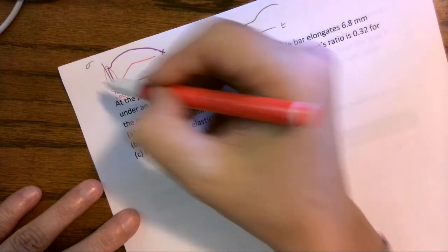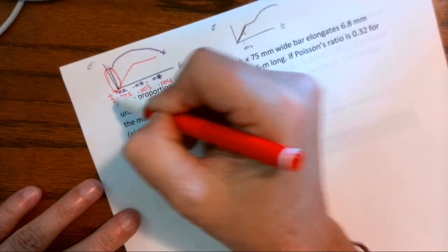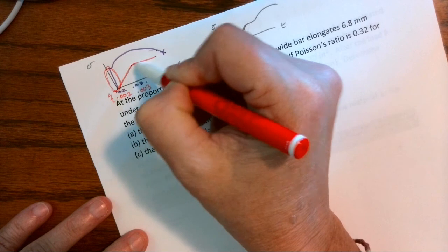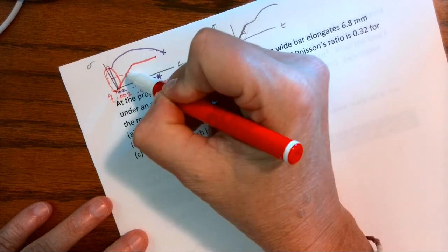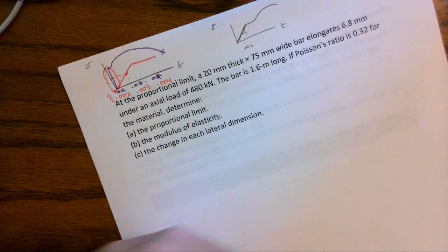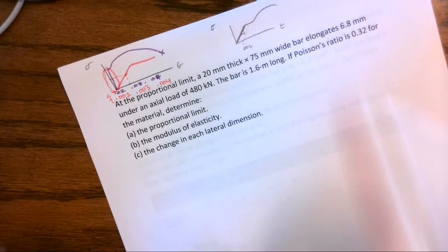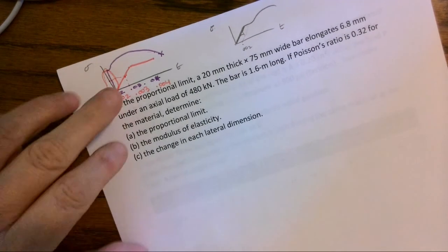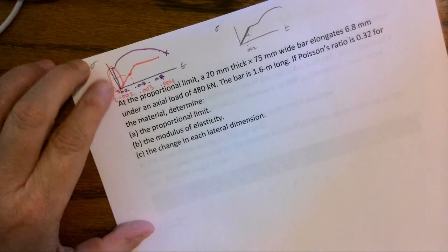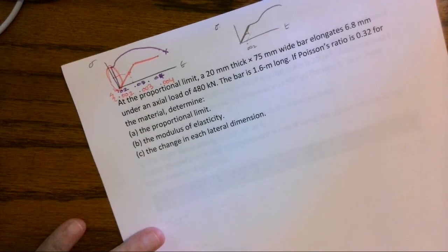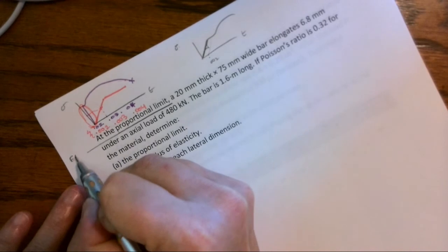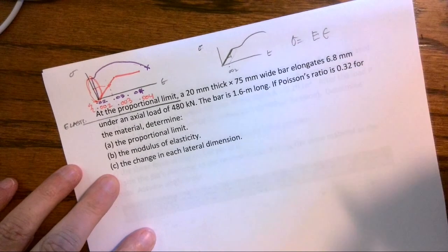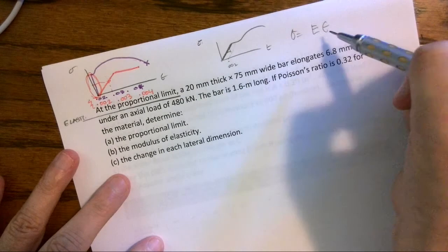So we take the elastic region, we change the scaling of our strain. That way we can actually focus in on the elastic region, so that if I want to know at this stress what the strain is, I can actually read those numbers. They're both the same material. It's just this bottom curve is zoomed into the elastic region. And if you look at the scale at the bottom, it's going to tell you, based on the color of the curve, which scale you read. Okay, so at the proportional limit, we are still in the elastic region where our equations are valid. In the elastic region, stress equals E times strain. That's valid. Once we go beyond that, we don't use this equation.